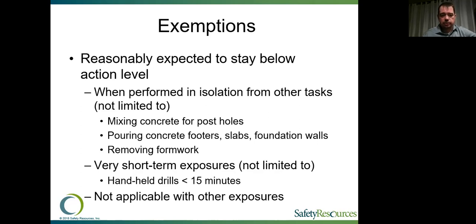If we have electricians that are drilling holes and they're going to do it for a period of about 10 minutes or so, that exposure may not kick them into the requirement of the rest of the standard. But if they're performing that task and doing 3 other things that would create other exposures, then all of a sudden those handheld drills do have to have all the right equipment, the collection systems and everything else that goes with it. So again, it's looked at as cumulative rather than breaking each of those tasks into their own singular application.